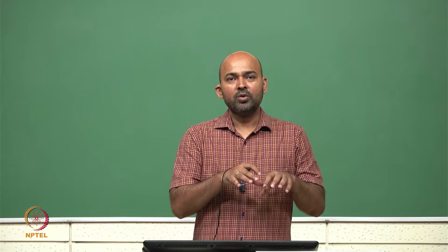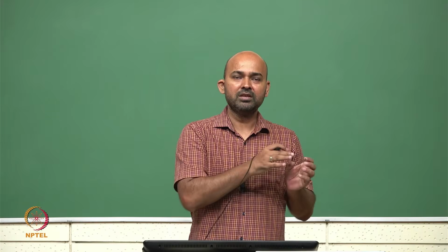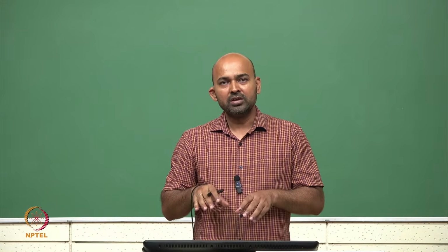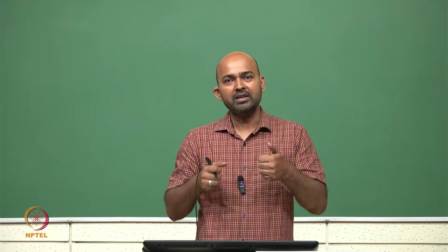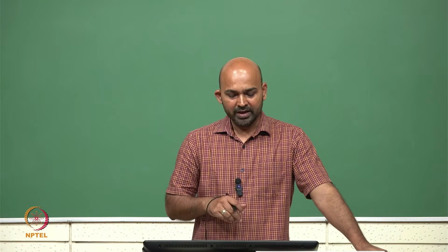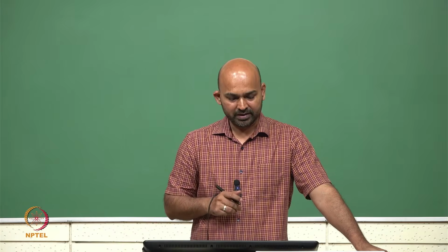Now the total equivalent of that circuit will be IN in parallel with the RN. So instead of, for example, in Thevenin theorem, where we have Vth in series with the Rth, in Norton theorem we have IN in parallel with RN. So this is the only difference. Other things are very similar. For example, we need to turn off all the independent sources in the circuit. Let's see one example for this Norton theorem.